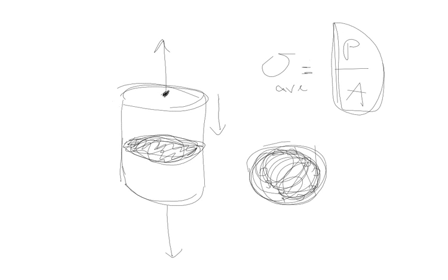So when it comes to shear stress, you can't assume that the average is also the exact value that you have over the whole cross-section. What you're going to find later on is that it actually varies from 0 at some locations on that surface to some maximum value at other locations. So it's a huge difference.